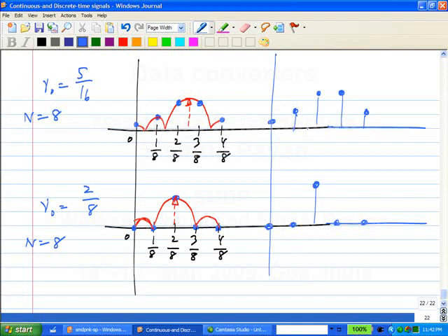Obviously the lower one. Okay. So there is bad news that there is a lot of leakage, but the good news is that there are certain frequencies for which the leakage is 0, because you are sampling only where there is 0 leakage. Okay? And what are those frequencies? What are the good sinusoidal frequencies?